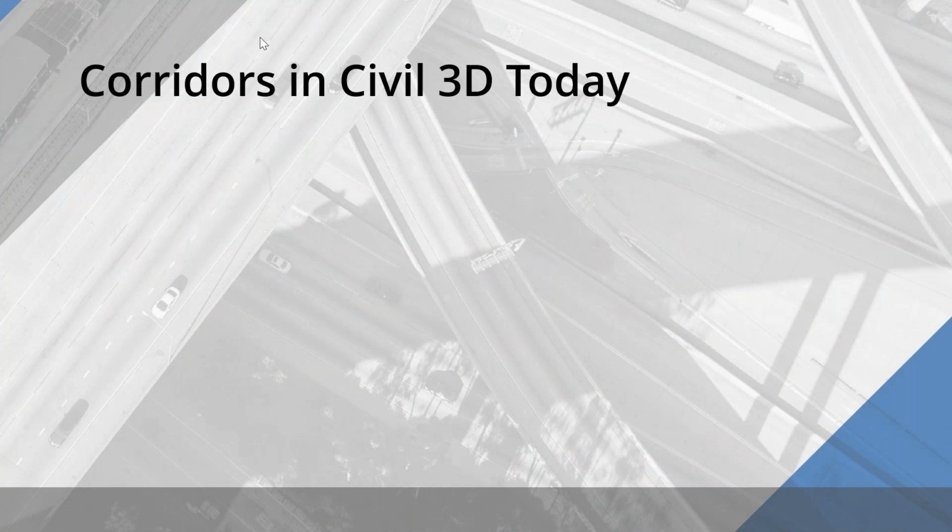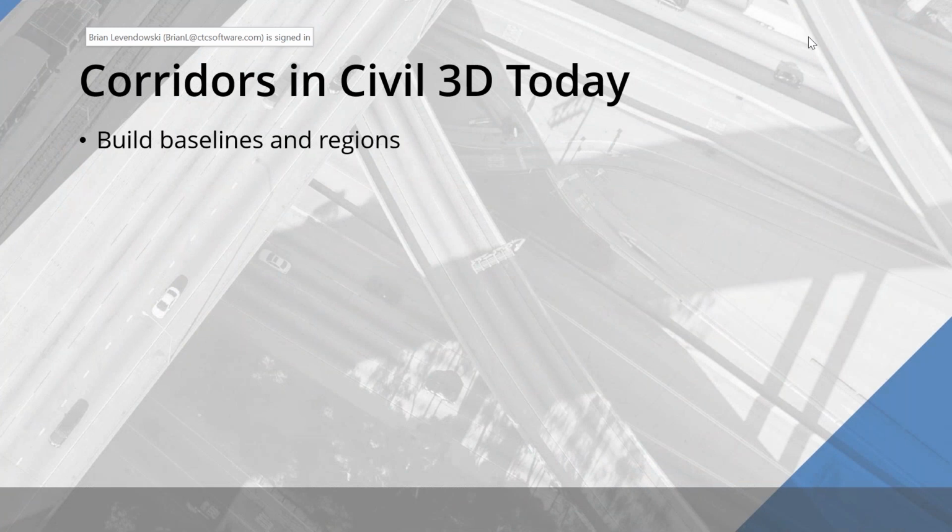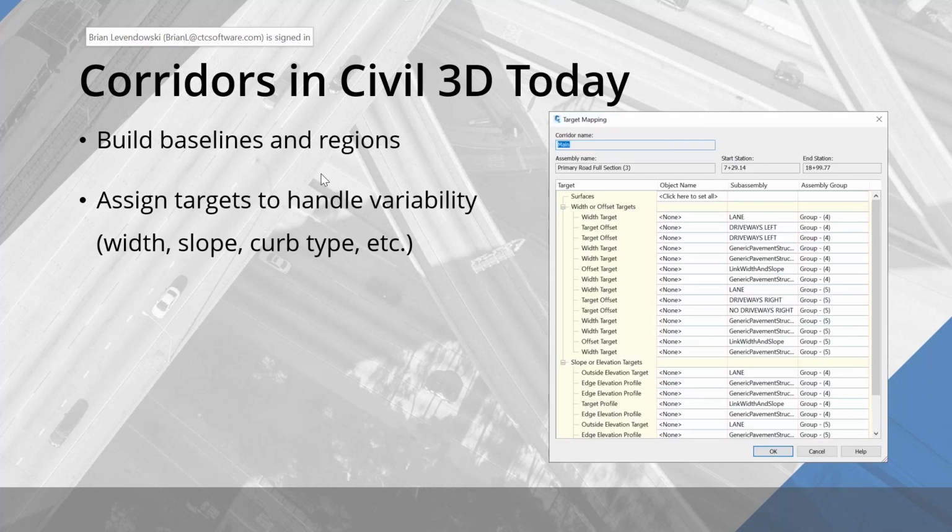I want to start by talking about what corridor use is like in Civil 3D today. We start by building baselines and regions in our corridor from alignments, profiles, as well as assemblies. We then start assigning targets through this interface that you've seen to control things like variability and width and slope and curb type. And we do this manually. We assign to one subassembly at a time. We go into here, we click where it says none, and we assign targets.